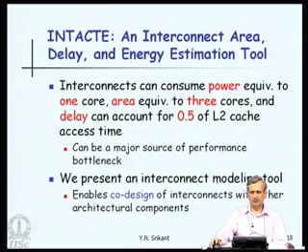Now, we move on to a tool called INTACTE that we have developed. This is an interconnect area, delay and energy estimation tool. It is well known that interconnects consume power equivalent to 1 core and an area equivalent to 3 cores, and the delay can account for half of the L2 cache access time. In other words, interconnects can be a major source of performance bottleneck if they are not designed properly.